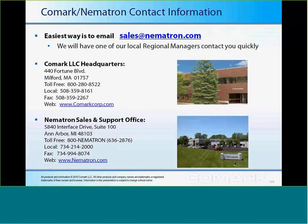Our products are tested by UL and approved by UL for a temperature, so you know the ignition temperature that they'll see, that they don't cause sparks. And then the ATEX is actually a European standard, which is tied to IECEx, which is an international standard for those hazardous locations. So you might see something like that in a paint shop or a chemical facility, and so a standard off-the-shelf TV type monitor or even a computer is not going to have those types of ratings, will it? That's correct.